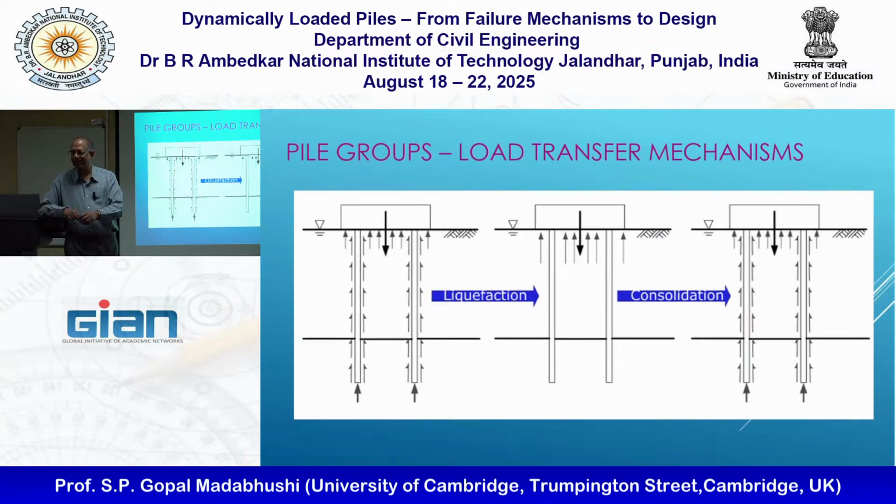But say I made my pile cap quite small, say I got a 3 by 3 pile group with a cap, and I got only a tiny amount of net area, then I can't get enough capacity. Then also it will settle, right? So whatever can go wrong will go wrong. That's why I'm quoting Murphy's law. It's basically that the soil is not wedded to one failure mechanism or the other. Whatever is easiest, it will do. And that is the point of these. Okay?